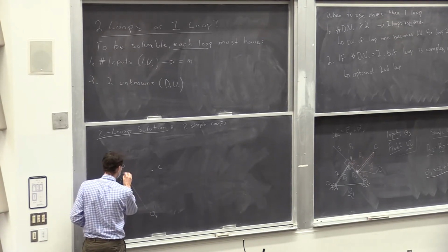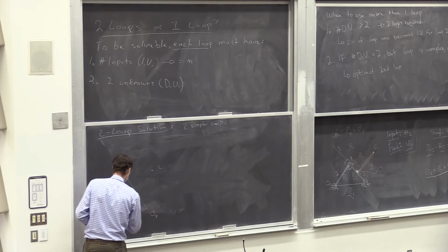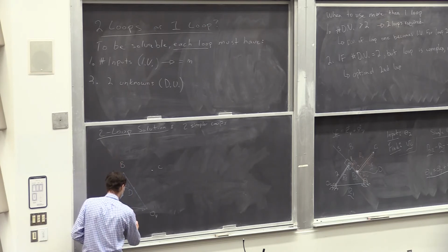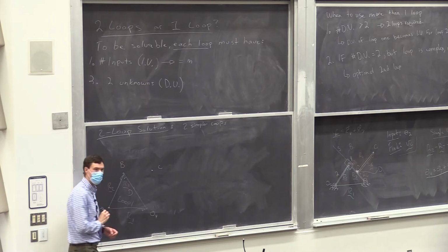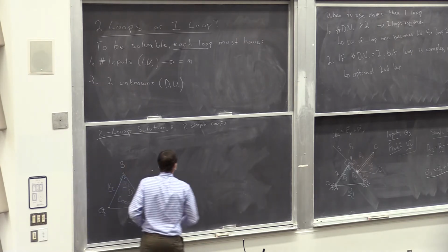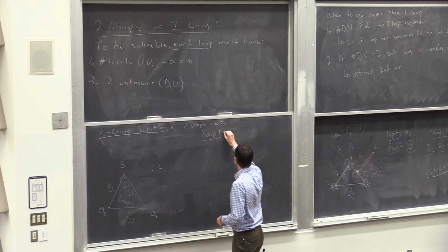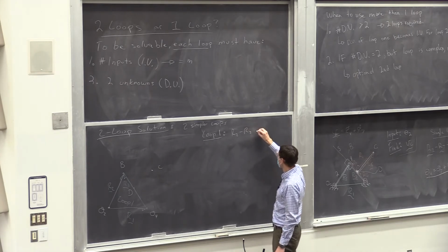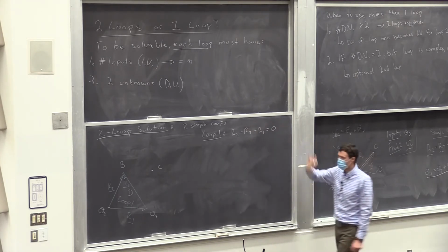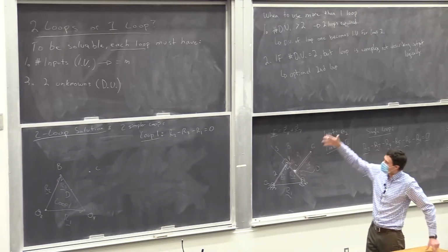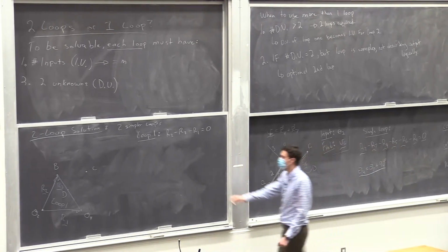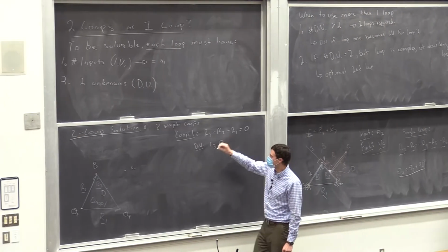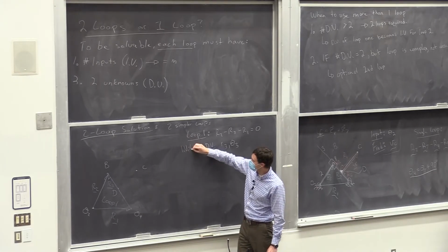This is the one that we solved last week. So we'll call that loop 1. We know it has 2 unknowns, 2 dependent variables. That's the length of 3 and the angle of 3. That's what we solved last time. And the input, of course, is theta 2.